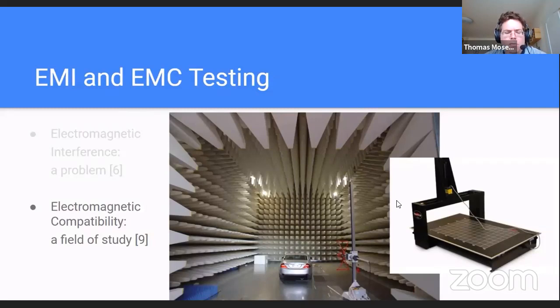The chamber, on the other hand, is meant for large-scale devices. The readings are done with a fixed antenna. The tested object is commonly placed atop a slowly spinning circular platform, which rotates for the radiation to be collected from all sides. The chamber is built as a Faraday cage padded with absorbing material, as to avoid wave reflections and external influences.